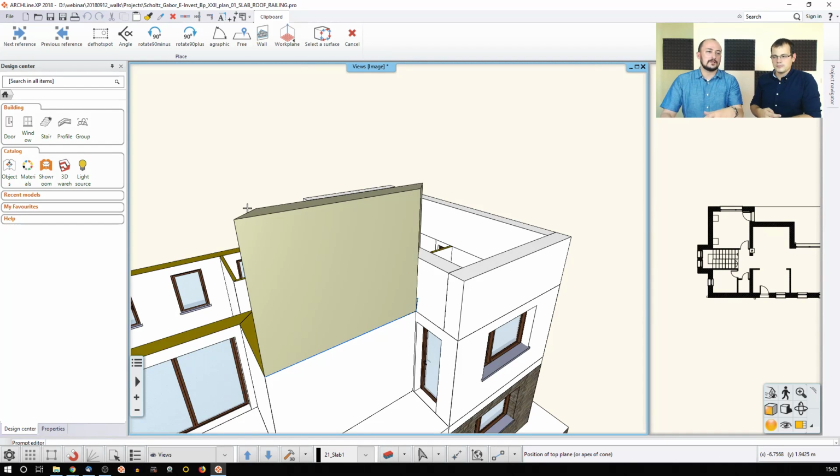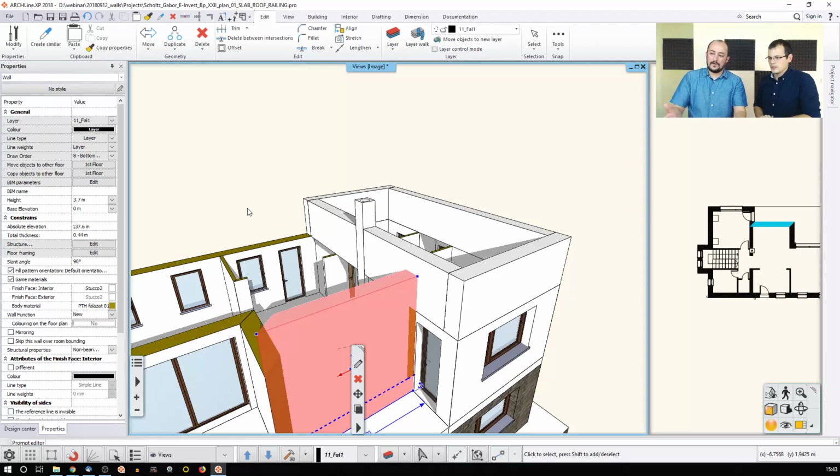a wall, and this is actually answering a question that we had earlier, how you can offset a wall with a certain value. This happens the same way. You just pick something and you move it. You tell the intention where you would like to relocate it, even if it's height or the position of the wall. You just elevate it, and then you tell the value. You don't have to click anywhere. You just tell it's taller, and then you type, for example, 1, because now we are working in meters, and now it's 1 meter taller.